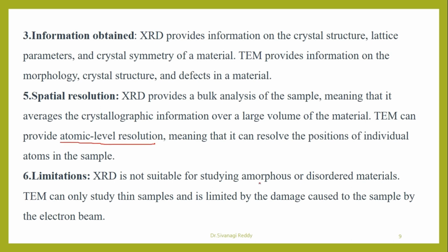Then limitations: XRD is not suitable for amorphous or disordered materials. TEM can only study thin samples and is limited by damage caused to the sample by the electron beam. In a TEM we use high energy electron beams.